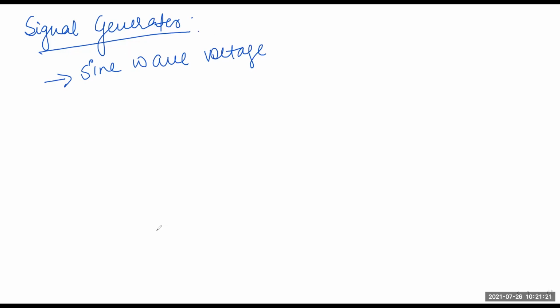Now the question comes, why do we use a signal generator? There is definitely a standard signal generator. This kind of instrument is provided with means of modulating the carrier frequency, and the modulation is indicated by a meter. Modulation may be done by a sine wave, a square wave, a triangular wave, or a pulse.